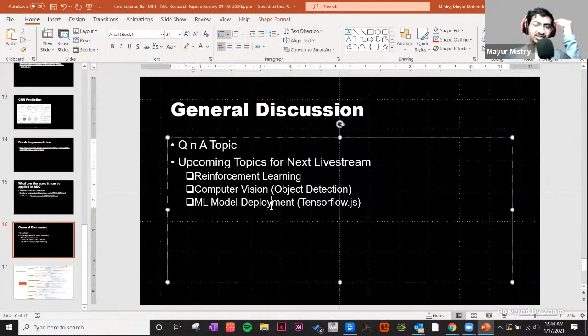So in one of the hackathons, what I did was, from Grasshopper, I was requesting information for the input and output of the machine learning model. It was a style transfer. The input image was in Grasshopper, then the information request was sent out of the Grasshopper environment, and I was running Python code locally on my laptop through a Flask server. That Flask server computed the style transfer image, and then the output was sent again into the Grasshopper environment. So that is one way if you want to use existing TensorFlow models.